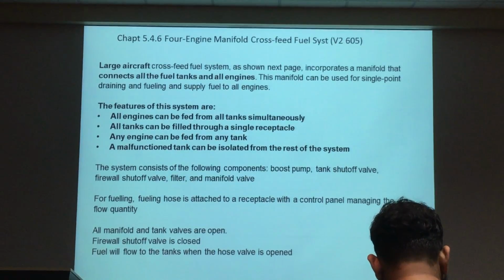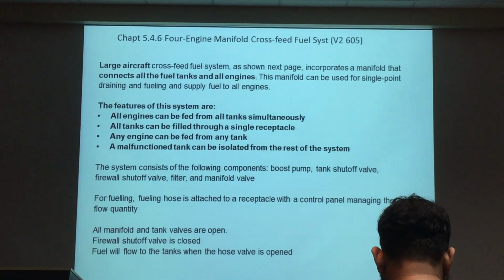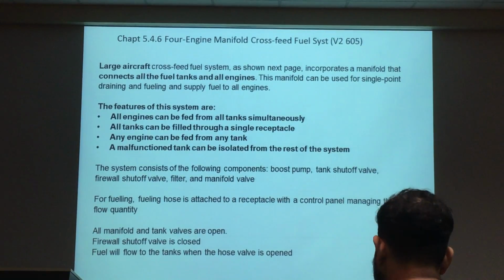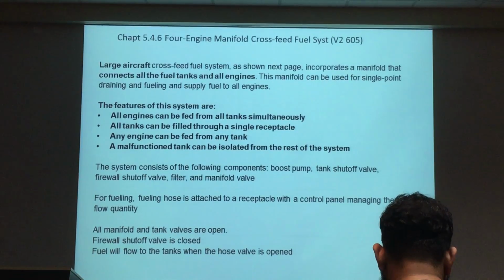Any engine can be fed from any tank. Yeah? One tank is enough to feed all the 4 engines. Let's say you got 4 engines. This is in terms of fuel safety, redundancy. If all the fuel boost pumps fail and there's only one pump left, that one pump must be able to feed all the 4 engines. We are talking about the fuel boost pump, not the engine pump. You got to push the fuel from the fuel tank towards the engine by using the fuel boost pump.